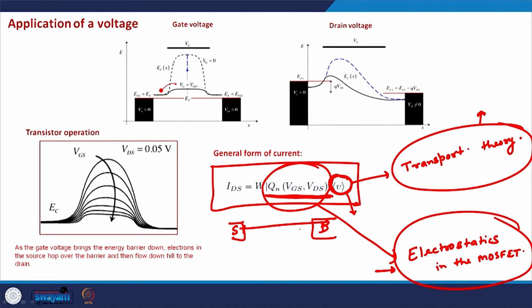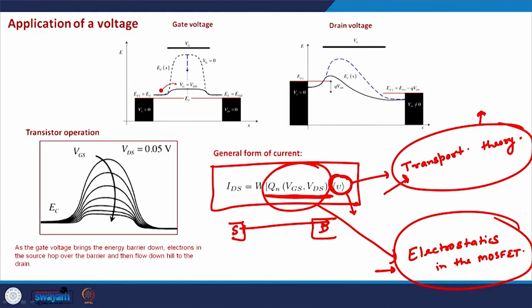Nowadays, because of scaling, because the size of the MOSFET is reducing, the transport is changing fundamentally. In conventional transport theory the diffusive transport is assumed by default, but that is no longer true, because nowadays the channel length is smaller than the mean free path of electrons, and ballistic transport is quite common. So, this needs to be revised properly, and that was one of the major goals of this course.